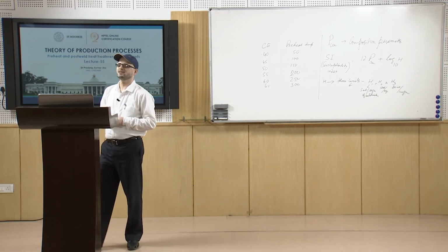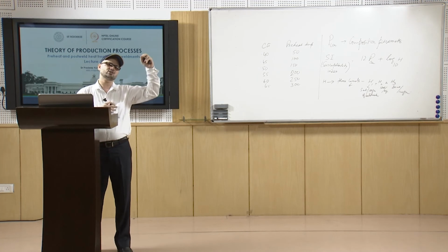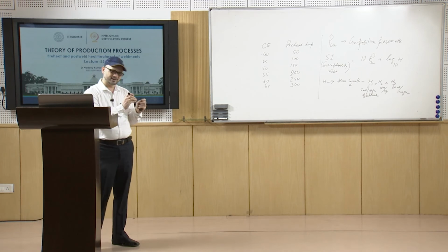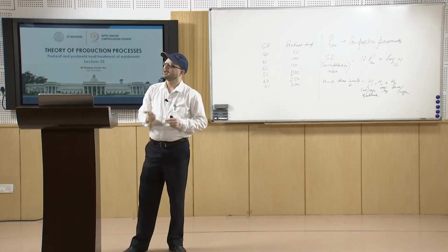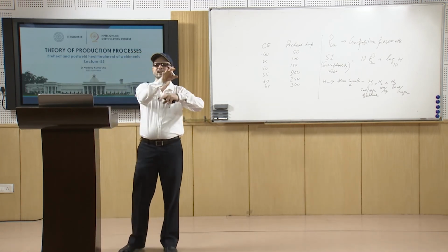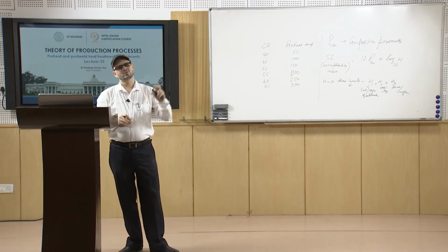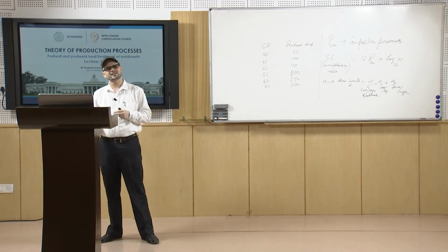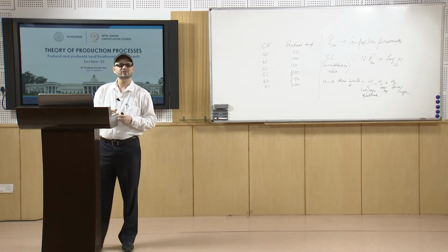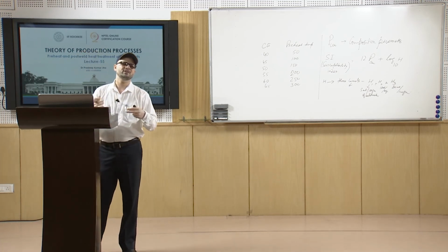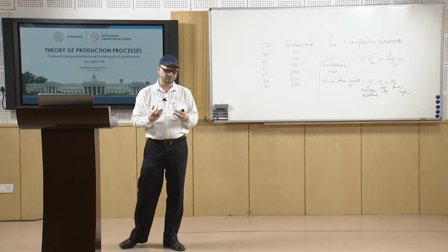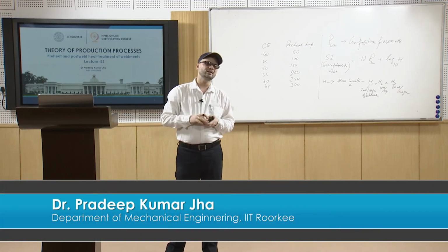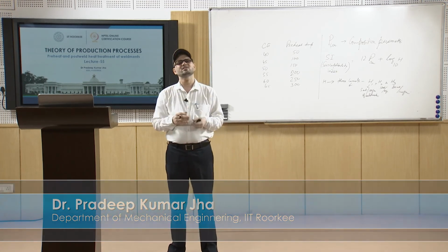Similarly, when we talk about martensitic steels, you cool down below the Mf, hold there for some time, and then heat to about 750 degrees centigrade and stay there for a certain time. Normally, 600 to 700 degrees centigrade is used, and it differs for different types of steels. You maintain the temperature for some time and then cool in a controlled atmosphere so that the stresses are relieved.